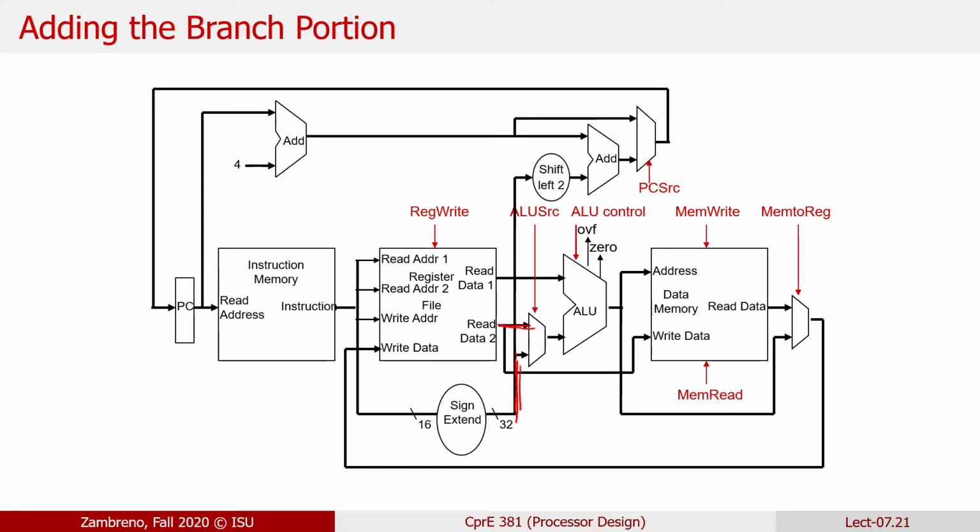For our data path in the single cycle processor, we're supporting both. We know that for any given instruction, we either want just one path or the other. That's our if condition, right? If it is an R type instruction, we want that default path of register output to the second input of the ALU. Because for all of our R type instructions, that's what's expected. There's an RS and an RT field. We use those to read from the register file, and that's our input to our ALU.